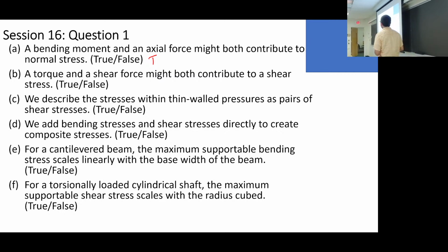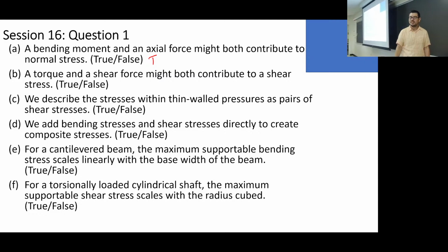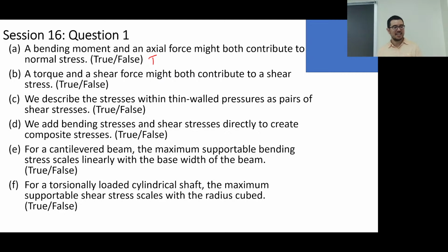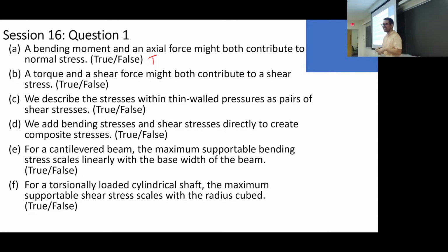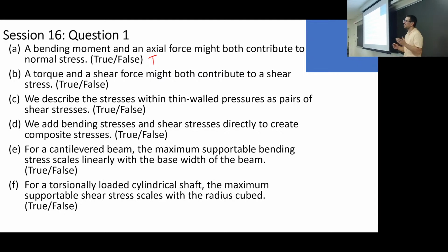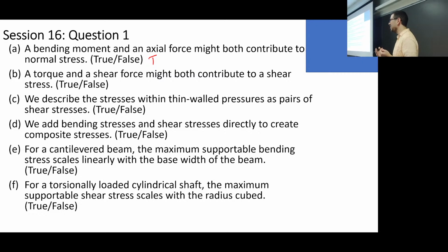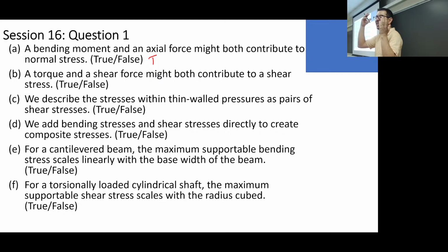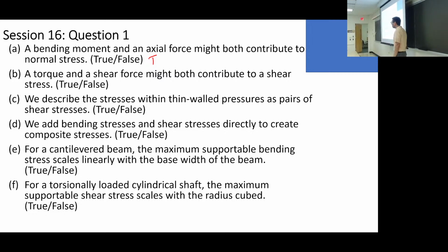Okay, a torque and a shear force might both contribute to a shear stress. What do you all think? I'm gonna go with true. Why do you say that? Because it could, because it has the word might. So now you use the opposite logic that I would use for superlatives. When I say might, what is an example where this could be true? Absolutely right. Torque, think shaft. Let's think shaft. I've got a shaft that's being twisted with a torque.